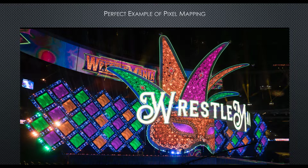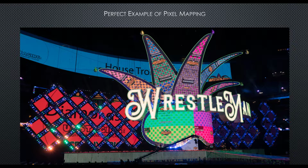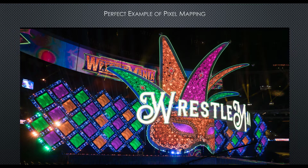But the signal that's being delivered to us is completely broken up into different pieces, and you can see this in the goggles here: goggles top stage right or goggles bottom stage right. Those are 1920 by 800 pixel sections, and these tiles are 80 by 80 pixels. It's a ROE MC7 LED screen, which is 80 by 80 pixels, 600 by 600 millimeters in size. It's 800 pixels tall, so we're doing 10 tiles on one raster and 10 tiles on the bottom raster. So that's 2 completely separate outputs from a computer, such as a media server like a Hippo or D3. And you can see how it combines so that you don't even see the seam in between.